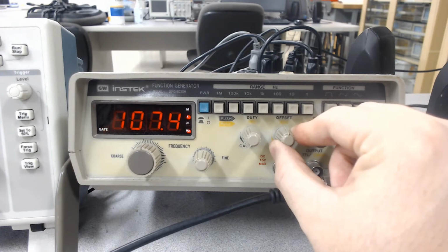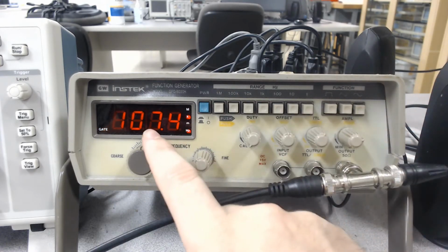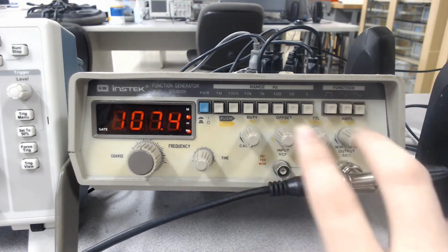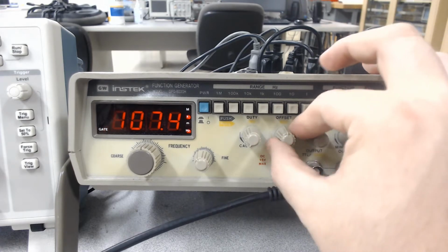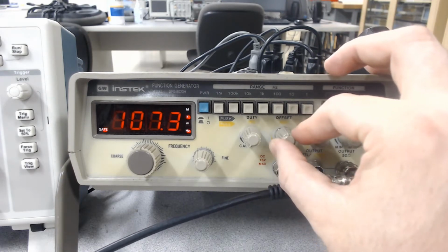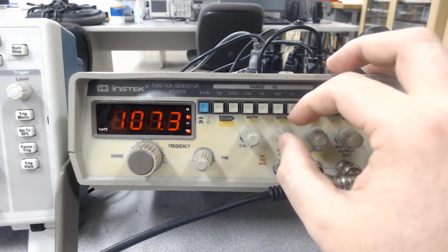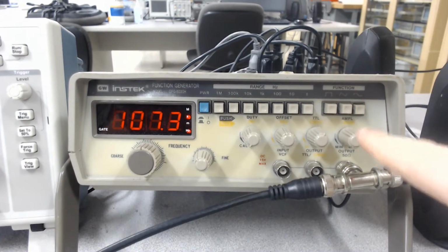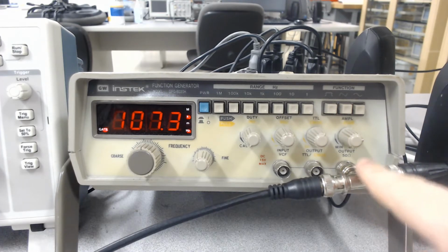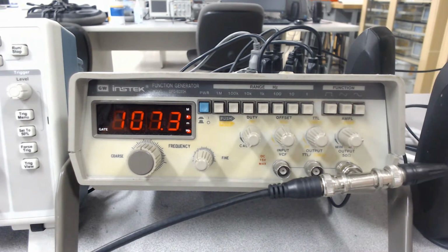I'm going to show you this more when I'm zoomed out so you can actually see what the oscilloscope is showing, because the only thing you can really see from the function generator is the frequency. You can't really see what the amplitude, offset, and duty knobs are doing, but you have to pull these knobs out in order to change the signal. It will twist if it's not pulled out, but it has to be pulled out to actually change the signal. Obviously, this is the output knob, so it will be outputting directly to the oscilloscope, like I mentioned earlier.